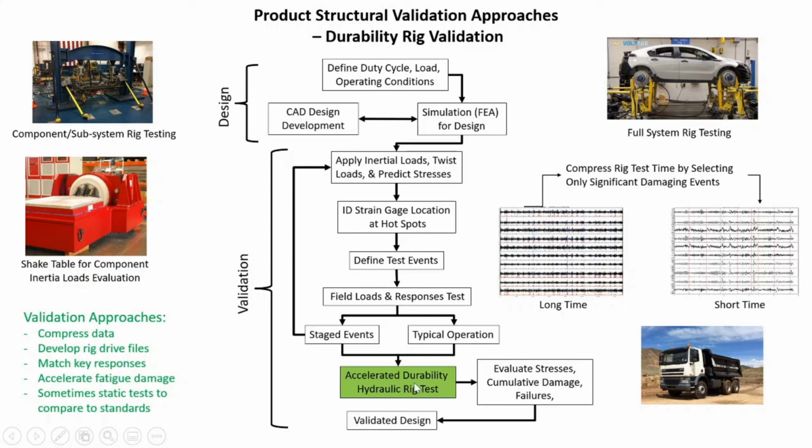So we want to be sure that responses that we had measured out in the field are matched by the loads that we use to drive the hydraulic rig. In other words, we apply these loads and we make sure that certain key responses are showing the same behavior that we saw out in the field.